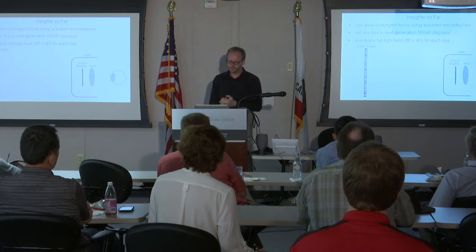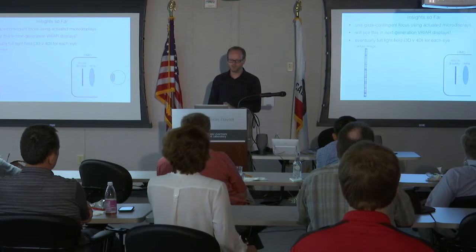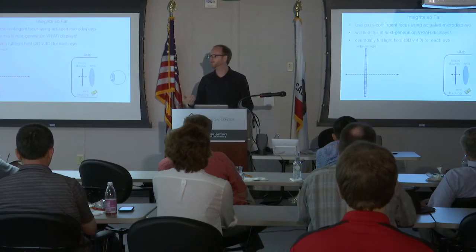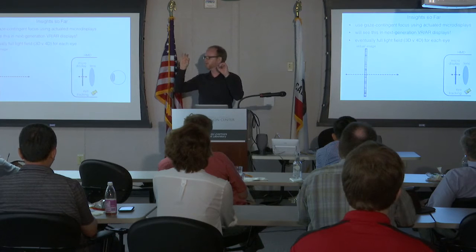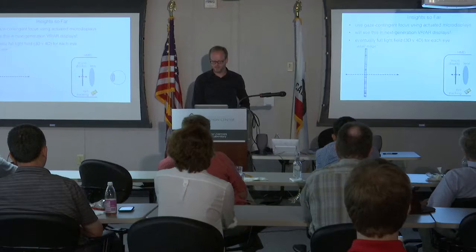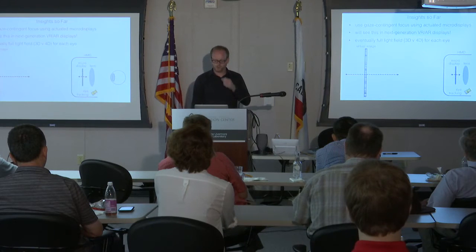these near-eye displays. So what we're going to see, and that's something we're working on with a bunch of industry collaborators right now, is basically adding eye tracking to the head-mounted display, and then probably actuating the micro display is better for a consumer product because the liquid lenses are pretty small. And when they're small, the field of view is restricted for your eye, so you can only see a small part of the image, whereas it's really important to get a wide field of view for all of this near-eye display stuff.